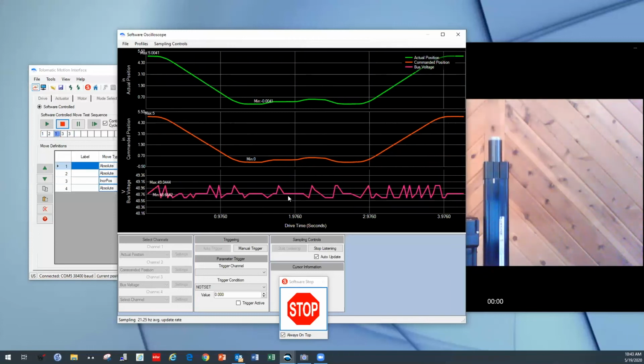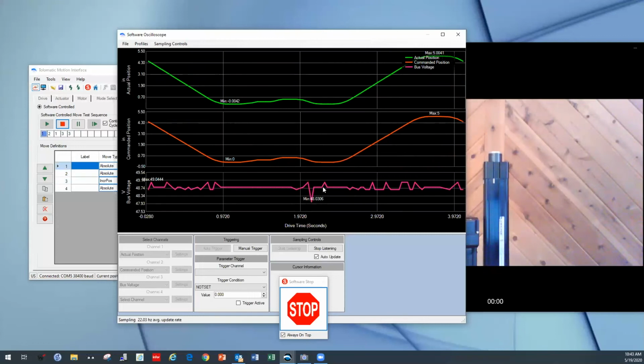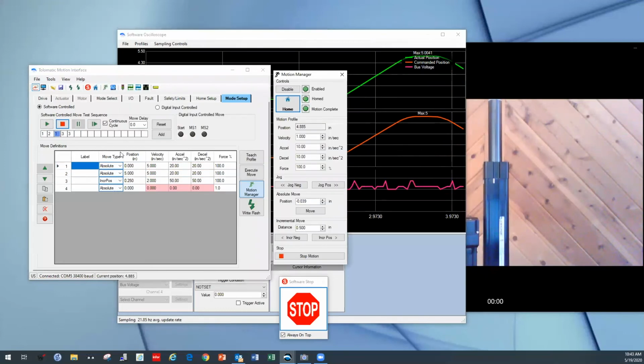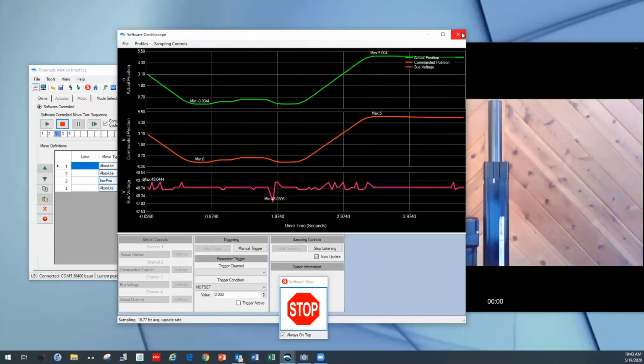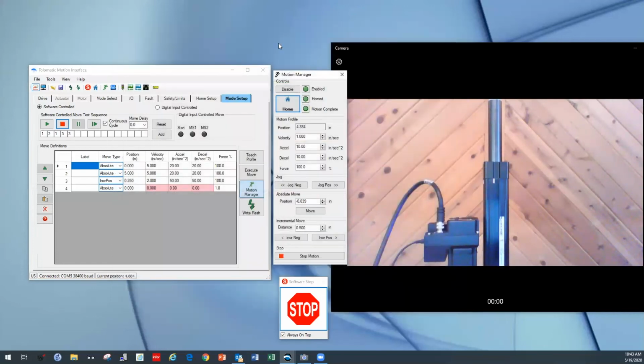If you saw spikes bigger than these, like going up 1 or 2 volts or down a couple volts, you'd probably want to consider some voltage regulation. So things like shunt regulators could protect the voltage from spikes, or you could have a stronger, larger power supply that allows you to pull more current from it and avoid the low voltage scenario.